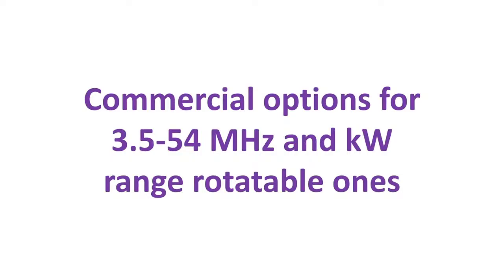Any parallel wire feeder can be used to operate on 7 bands using a tuner. They have also mentioned that best results are achieved with a symmetric tuner, but any other tuner with a balun also works well. Others have used coaxial cable with 4:1 balun for multi-band operation.